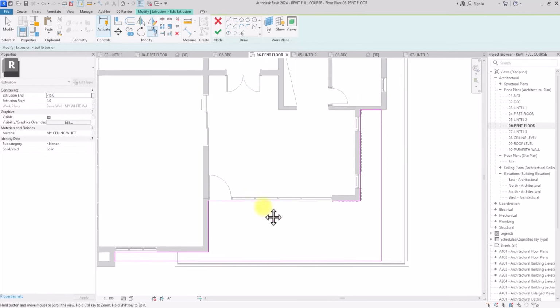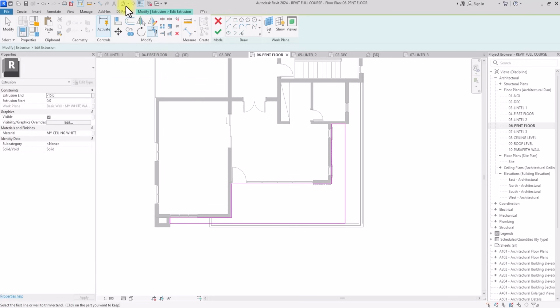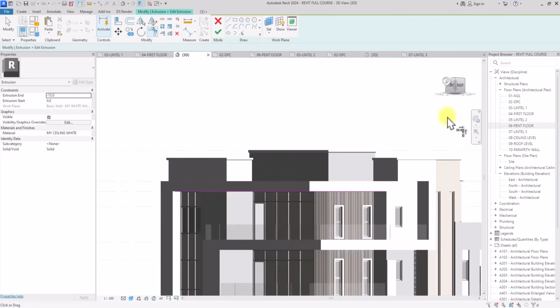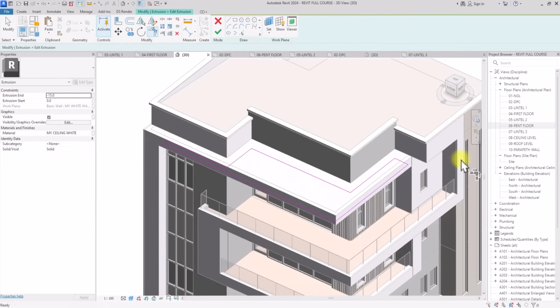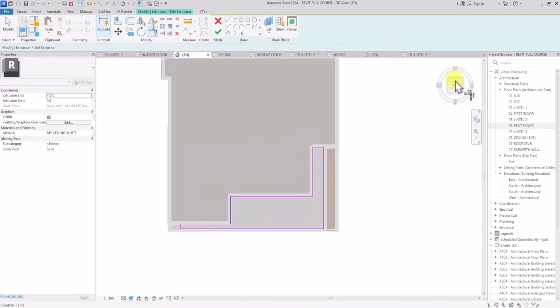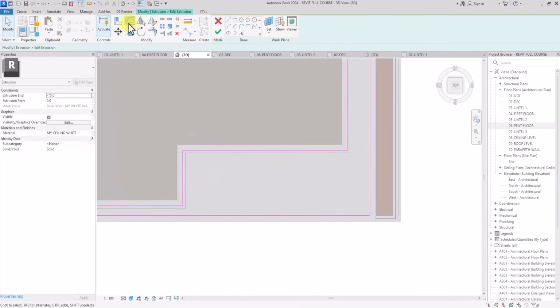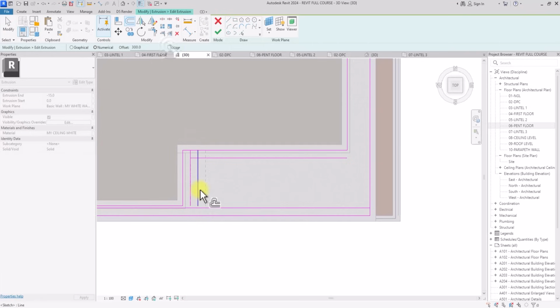So now we are also going to make provisions for LED lights, but I'm actually having a double mind on this because I want to make some perforations here for trellis and see how it will go. But since this place is very open, okay, I think I can do it. So instead of creating LED lights here, I'm going to make perforations for light trellis over here. So I'm going to make some openings. I'm going to change this offset to 300. And I'm going to offset 300 from here. Offset 300, offset 300. I'm also going to offset 300, uncheck copy, offset this to 300.